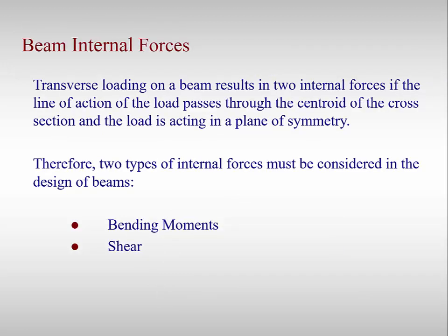All these loads result in internal forces that the beam must be designed for, mainly bending moments and shear forces. We will see in Lesson 20 that we usually select the member size based on moment and then go back and check the shape for shear. And shear is covered in Lesson 22.